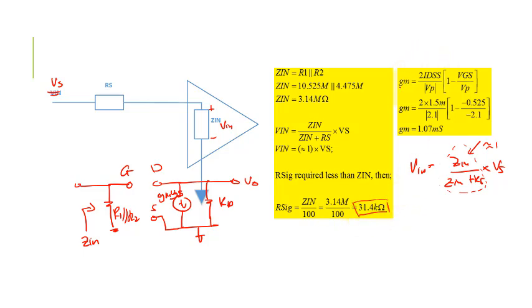And then we determine the value of gm. This one is the IDSS, and we obtain it from the datasheet. VP is the same, and this one is our VGS and also the VP, which we obtained from our previous chapter 1.